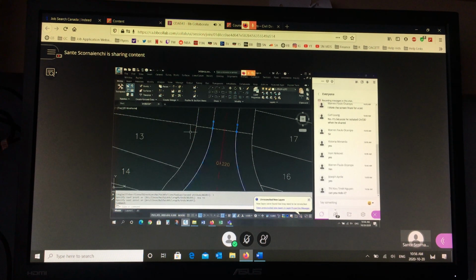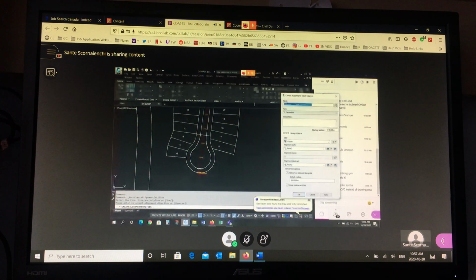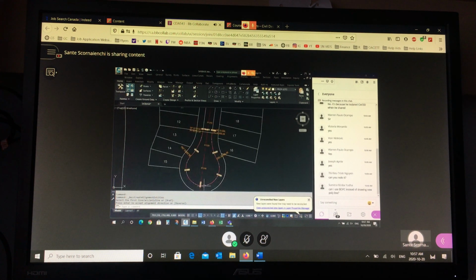A little bit more at the beginning, a little bit more at the end. To create the alignment, we go to alignment, create by polyline. I'm going to pick this end because I want 0 to be on this side so that the boulevard is on the left. There's the direction right here. That's correct. Enter. And I'm going to give it a name, Street A cul-de-sac. And then turn this off. Okay? I've created all the alignments so far. Say OK. And then just double check that it's going the right way. 20, 40, 60. Yep. Okay.